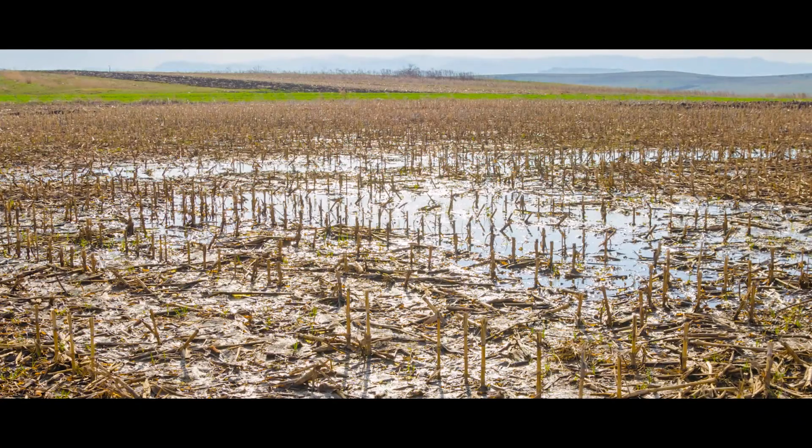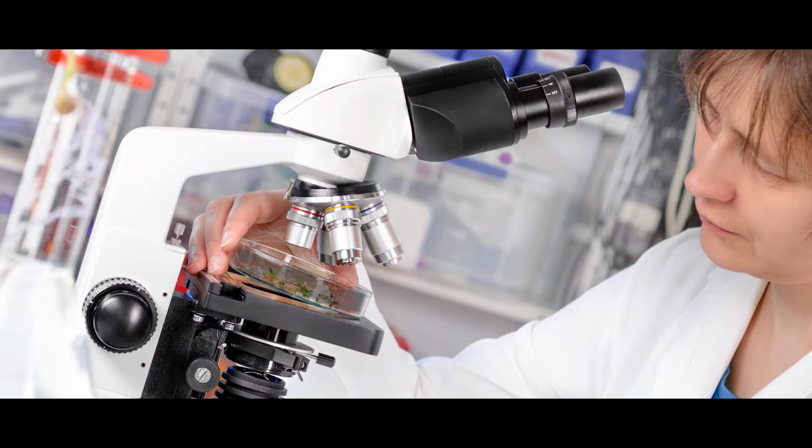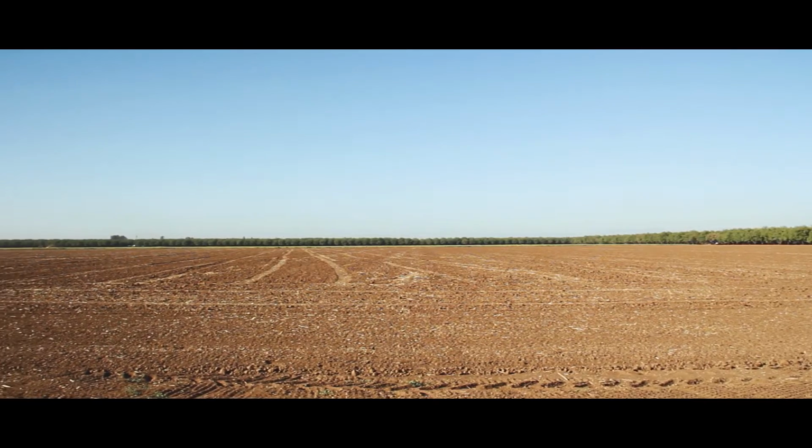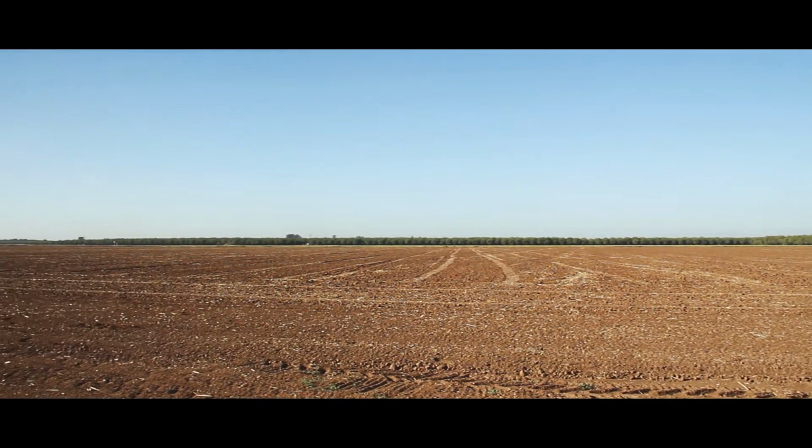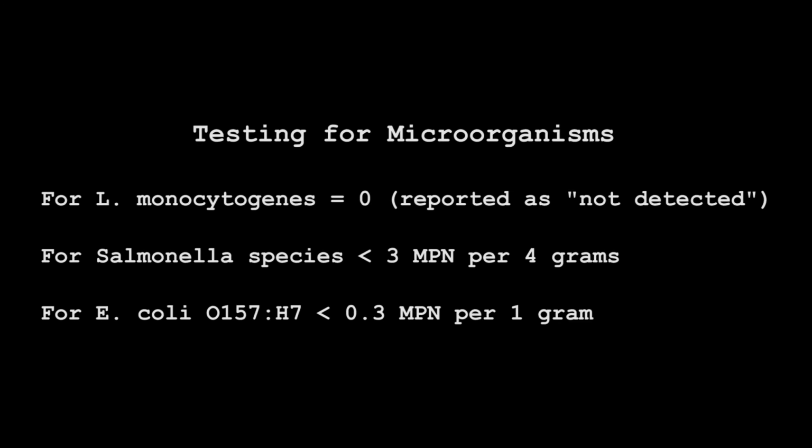The flooded area should not be planted with crops for human consumption for at least 60 days once the ground has dried out, unless soil testing has occurred. If soil testing is performed, suitable representative samples should be collected for the entire area suspected to have been exposed. Soil testing must indicate that the levels of microorganisms are lower than the standards for processed compost. If the results indicate the soil is not contaminated, the replanting time can be reduced to 30 days.